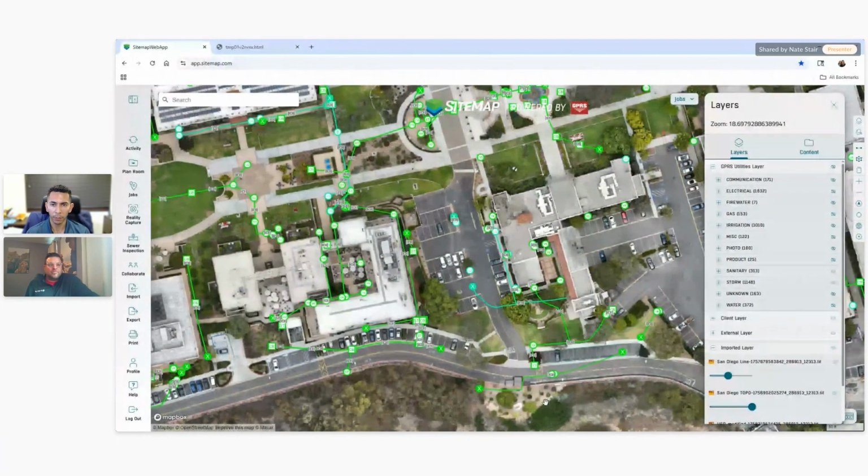With that pipe inspection, we were able to pinpoint exactly where it was, because it gives you data, not just the video, but it tells you how far in the pipe it's traveled. So we were able to bring our equipment, and the plumbers were able to clear that drain right there. Knowing exactly where the clog is takes a lot of the intermediate work out from the plumbers, of just shoving the jetter into the pipe and waiting until they feel it stop moving. That definitely saves them time and removes some of those question marks.